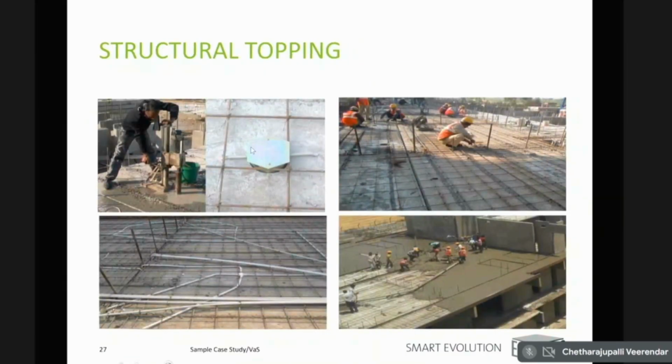And then you have the slab. Sometimes whenever you require coring on the slabs, it is preferable that you plan it out in the factory itself. If not, you can always do the coring at the site. And the slabs are placed one after the other. Each slab is 1.2 meter. On top of that, you are going to put a nominal reinforcement of 8 mm. You are going to pass all the conduits like this, and then you are going to make the screeding. The structural screed becomes an integral part of this requirement of hollow core slab or any kind of slab, so that it has a diaphragm effect and holds all the elements together.